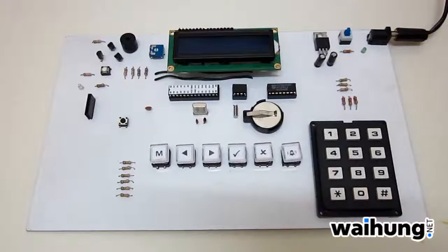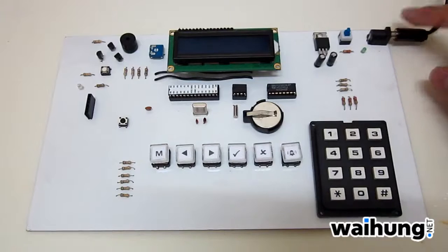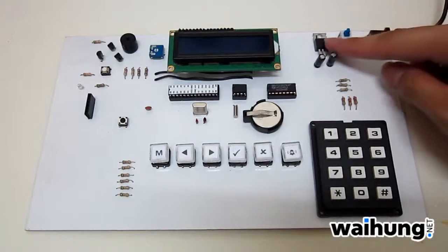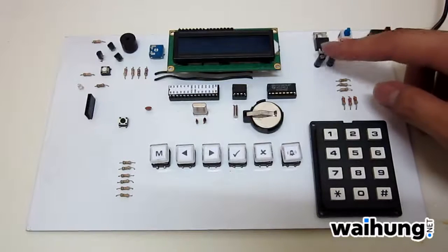Hi, this is my digital alarm clock project, and I'm going to show you around each of its parts. To start off, this is the 12-volt DC input jack coming in from the mains, the LM7805 voltage regulator with two smoothing capacitors for the input and output,